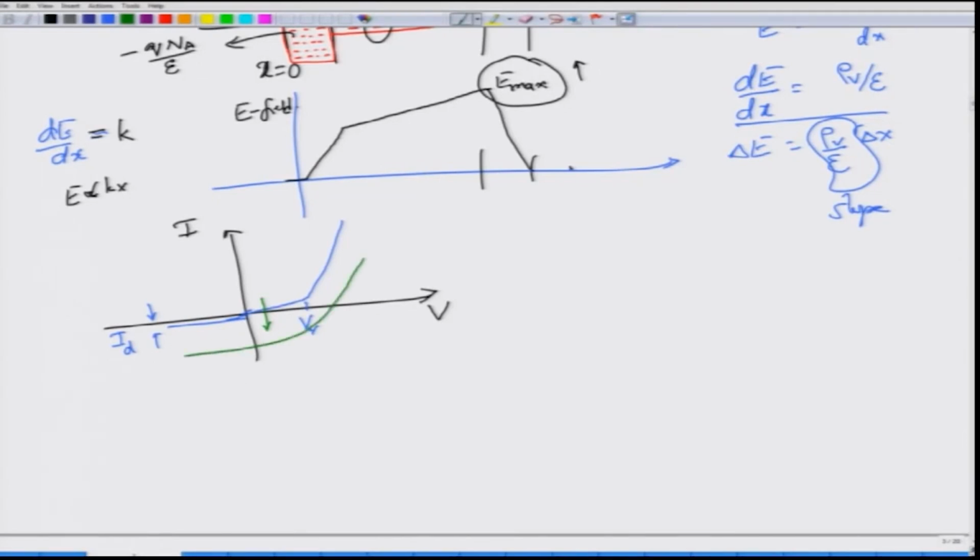So what you see is this type of a graph. Okay. This is of course exaggerated pretty badly. So what you can see is that the V gamma, the cut-in voltage that you would have seen for the photodiode without any illumination, would actually become larger and larger. At the same time, the reverse current will also keep increasing. Okay. This is the IV characteristic of a photodiode. Of course, you have to understand that the scale here on the positive side is in milliamperes, whereas the scale here is in the microampere range.